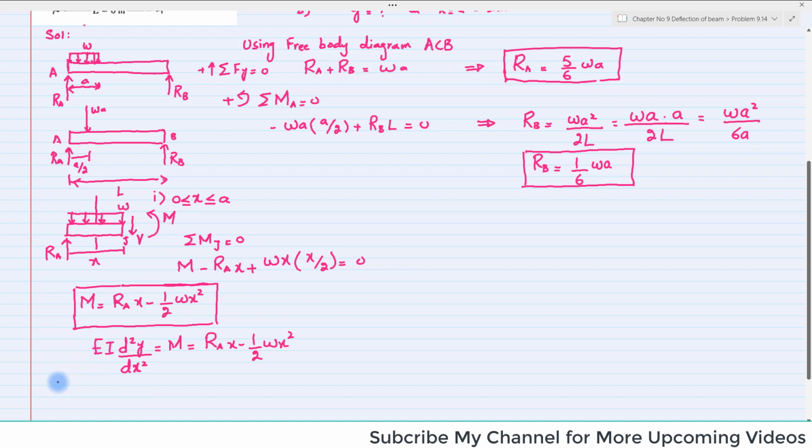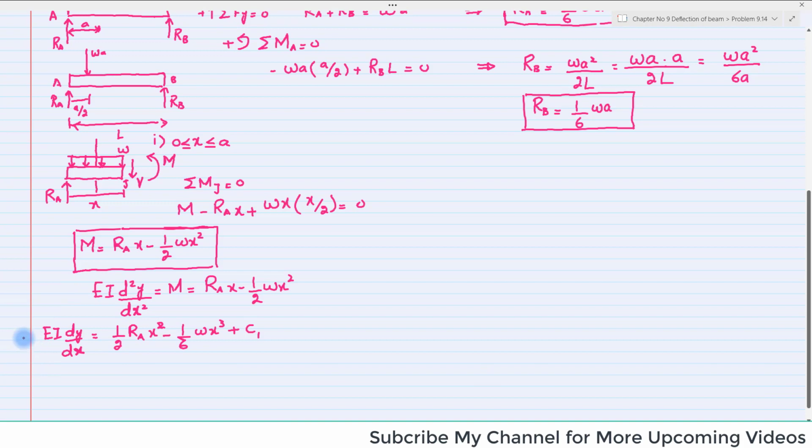Integrating it for the first time, you will get EI dy by dx equal to 1 over 2 RA x square minus 1 over 6 W x cube plus C1. Clear? Okay. Moving further, again we will integrate this equation.